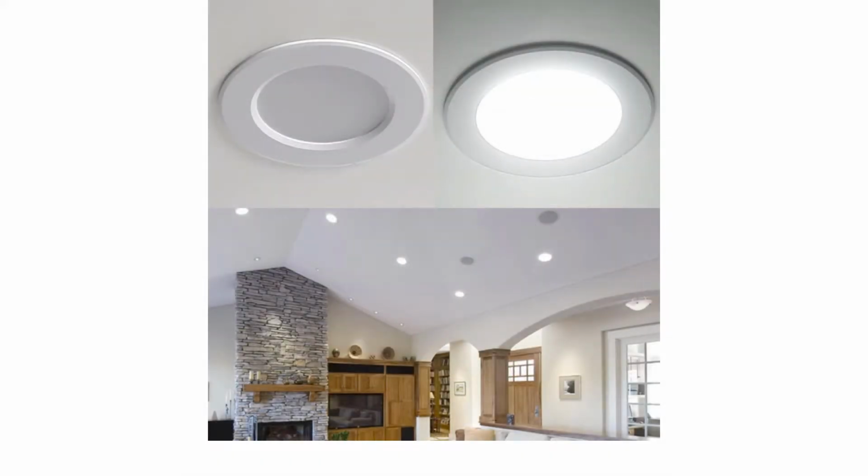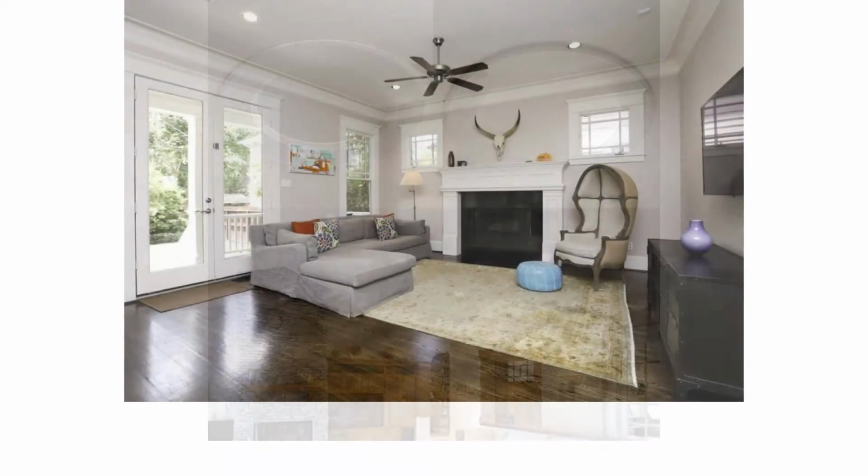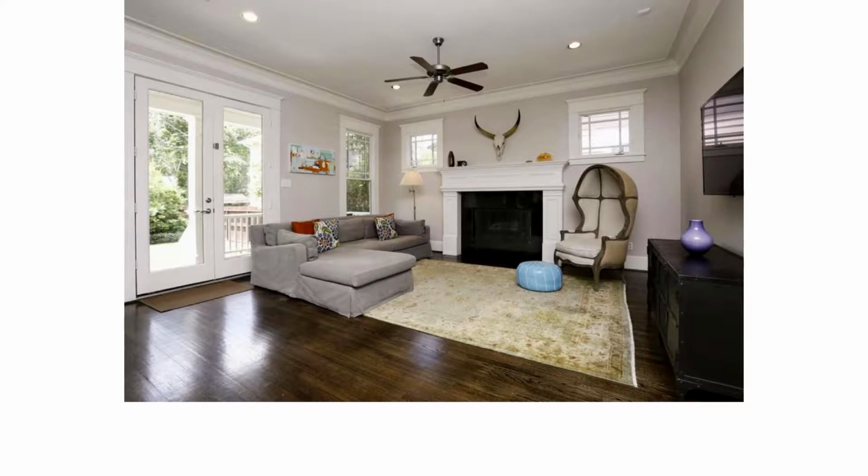So the other thing to consider is using a luminaire that is meant for its location. Sloped ceilings are the classic example. If you put a regular downlight in a sloped ceiling, it will be facing sideways. It will be facing at an angle. So be careful about that kind of stuff. Also, pet peeve of mine, don't put a downlight over a bed.